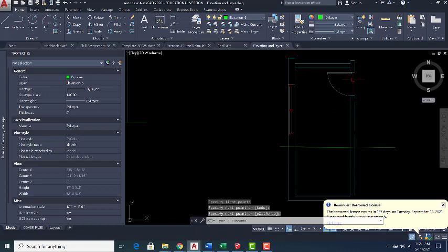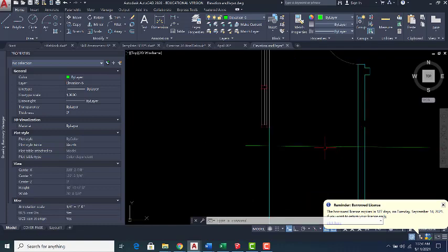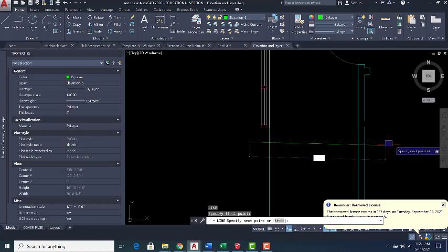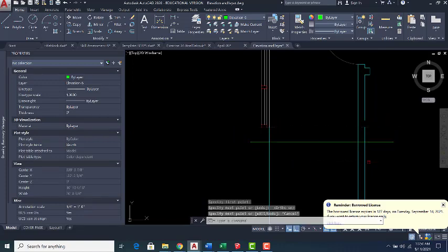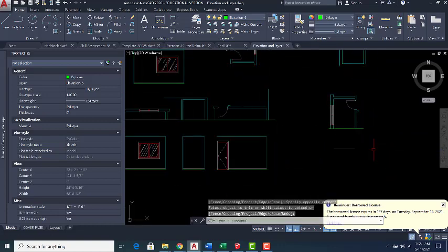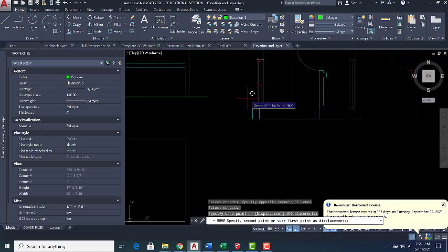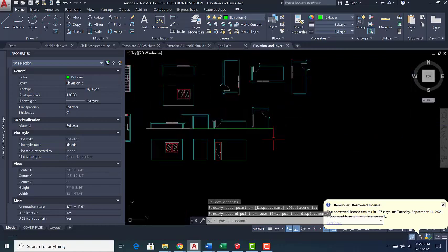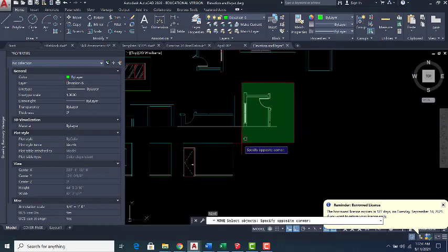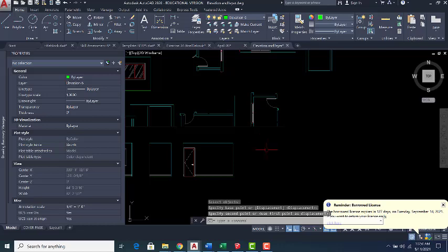I would avoid going inside the opening or windows, especially if I was doing architectural one, because then I have to spend lots of time doing all the detail, unless you want to show those details. Sometimes you have to, at least as an architect. So here you go. We delete all the extras. We delete this one. Then I move this guy and I place it here. Okay, now I'm getting too close. I would move it a little bit here.